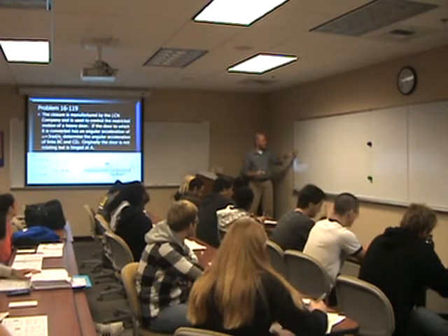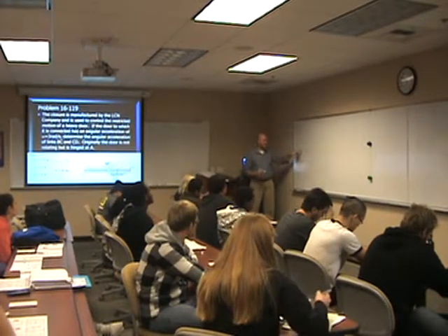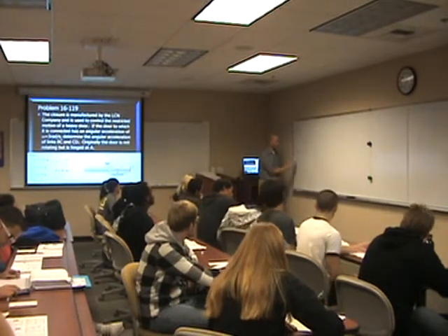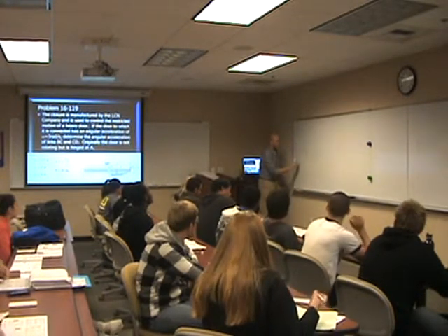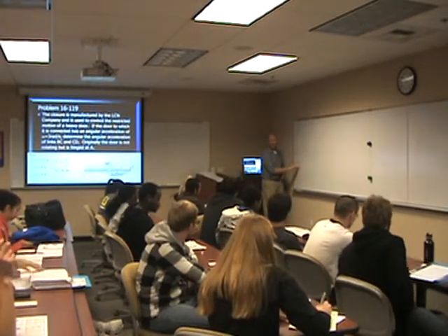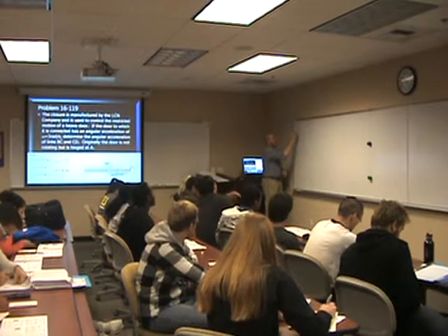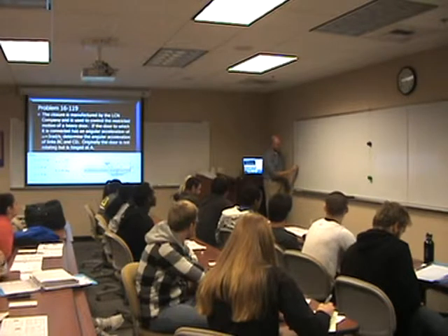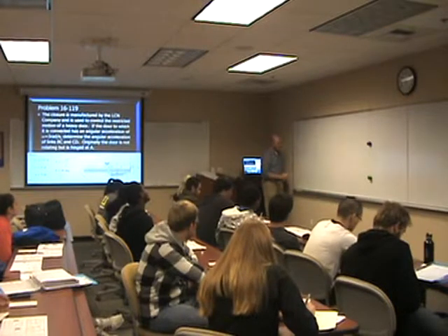So we basically have the acceleration of C equals the acceleration of B plus the acceleration of C with respect to B. Acceleration of C was going to be R4 times alpha CD, and we said that that was going to be going what? Your R alpha is always perpendicular to R, so that's going to be going up like this, assuming alpha CD is like that. So that's going to be going up to the right, at 60 degrees like that.